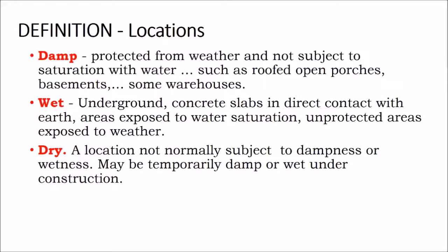Now, I can tell you from industry experience, the locations can trip you up and weather ratings can trip you up, because solar equipment is so robust and it is designed for outdoor use. So you might be buying inverters that are NEMA 3R or even sometimes NEMA 4 or even NEMA 6. So very robust, waterproof inverters. You may be buying microinverters or module level electronics that go up on the rooftop, and they're listed for the extremes and they're listed for the weather.